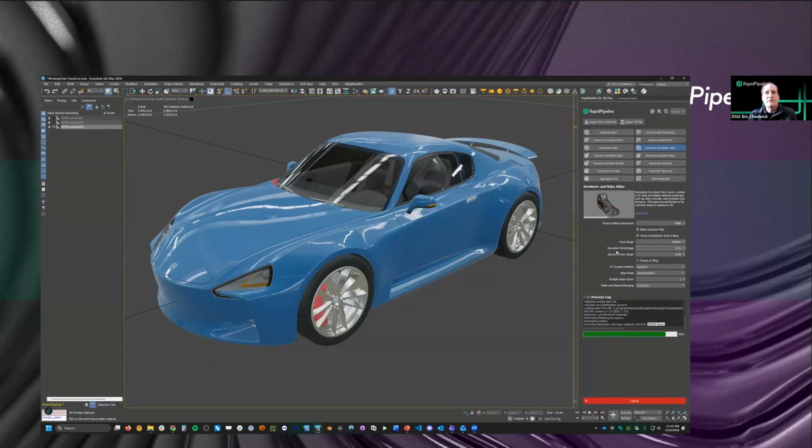That's what this is. It's an upper limit. And we've got something called deviation percentage, which basically looks at the surface and says, hey, I'm going to get under 200K, but is there even more that I can do based on a quality metric? So it's going to look at even flat surfaces or surfaces that are deviating from the original surface and how far are we allowed to deviate. And it might even go below 200K because of this percentage quality level. So if it can go lower than 200K, it will.